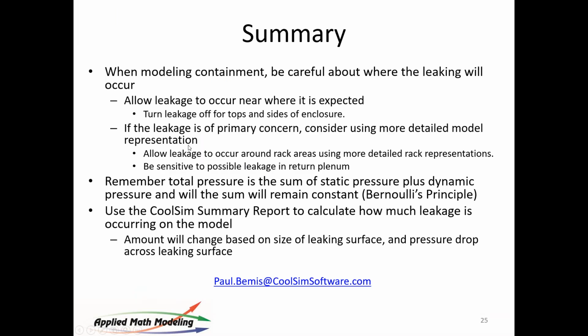So you need to model leakage. You can model it in a variety of different ways. You can let it leak around the rack itself. You can just let it leak through the containment, a fairly straightforward representation like I showed you before. Those are really fast. Remember that as you increase the level of detail, the amount of time, both in terms of development of the model and the runtime, will rise, because the runtime of the model is correlated to the level of detail you have in the room. The mesher builds a mesh, and the mesh is correlated to the smallest objects in the room.